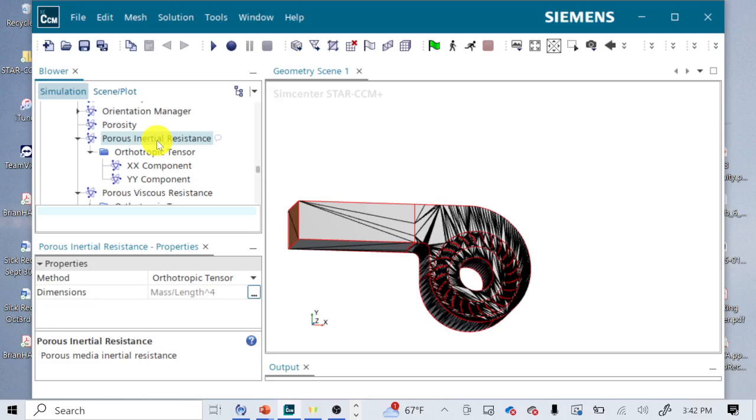So let's see if this all works out. This is in the numerator, not in the denominator. So it looks like that matches exactly, because this will work out the same. The units of viscous resistance are kilograms per meters cubed seconds, excuse me, times meters per second. So yeah, this does work out. That is how it does it. So it will calculate the change in pressure in any given cell in that area by the size of the cell times the product of the inertial resistance times velocity squared plus viscous resistance times velocity.